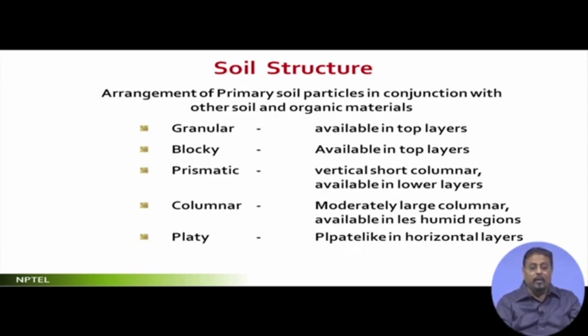One is granular. There may be even fine granular. Granular means we have the granules which are holding to each other, which are quite significantly large in size or of differential sizes. Generally this is the layer which we find at the top layer of the standard good earth or good soil. There can be even fine granular. That means you have the granular, but the particle sizes are very, very small. So, if you hold it, it almost comes out like a sort of dust. That is also possible. I am not going into that detail of it.